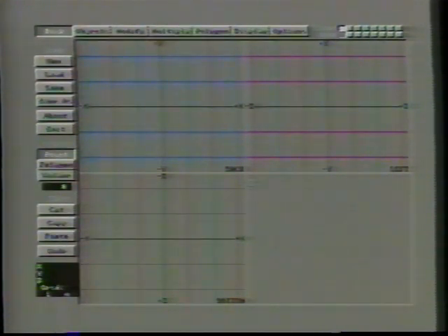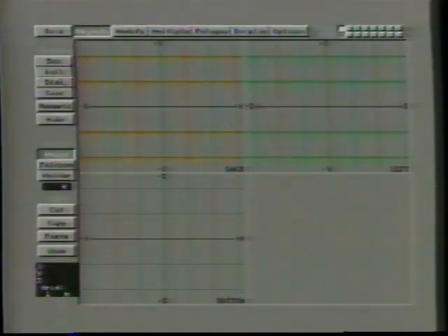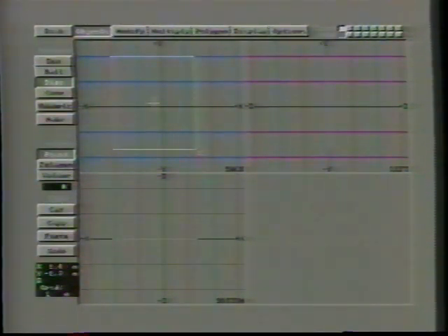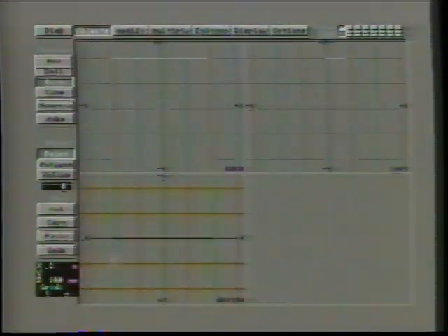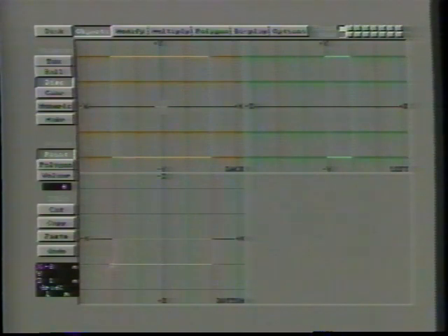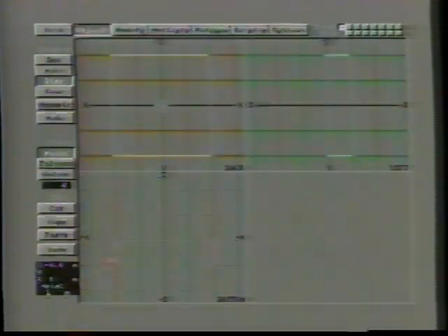I do this by selecting Disk under the Objects menu, and with my mouse pulling out a square that measures 4 by 4. I don't want the logo to be flat, so I'll also extrude the Z-axis by about a meter.